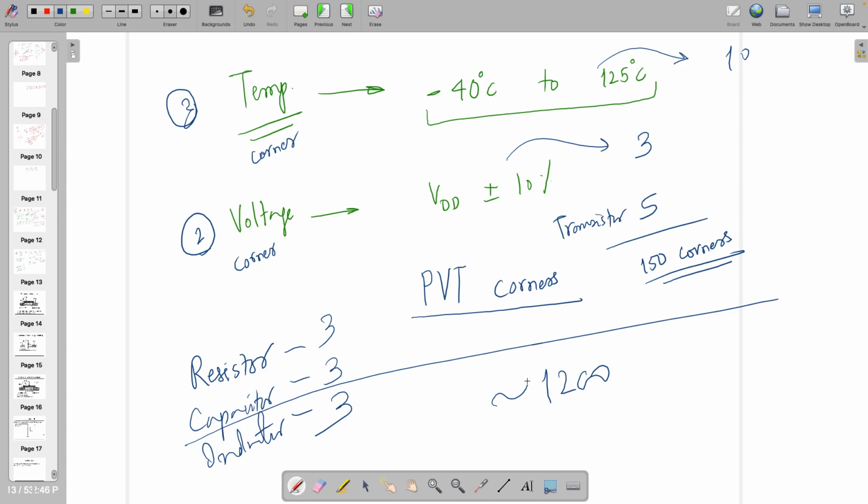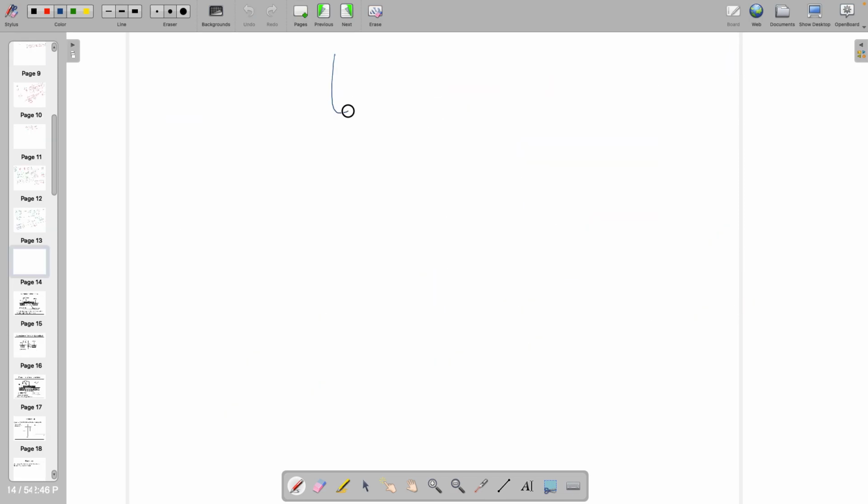But this is just a schematic, by the way. What you have done is for the schematic. Later on, once the schematic is working, you check the layout also. From layout, you get all the parasitic effects, and you run the PEX simulation, parasitic extraction simulation. You will run PEX and learn it in the other course, digital IC design.